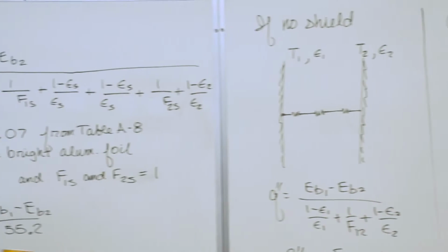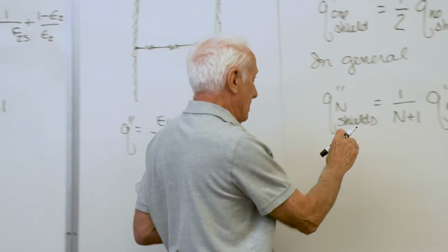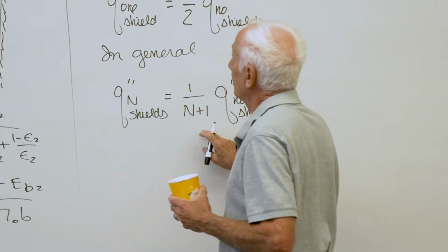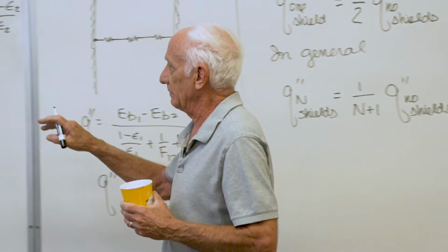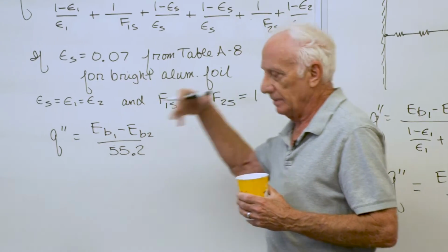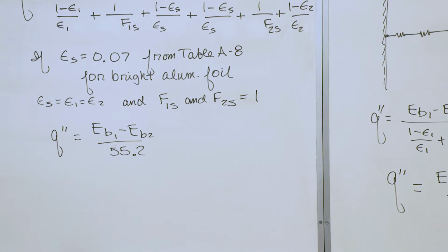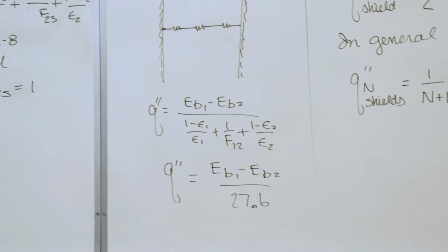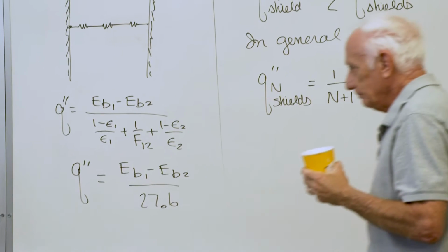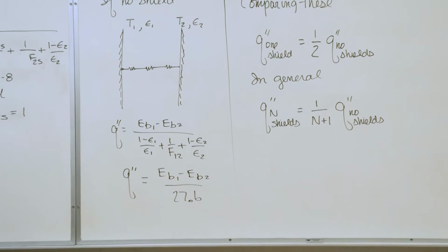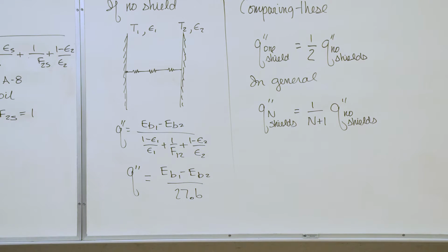So that's it. Now this equation right here is only valid if you let the emissivities be equal. If they're not, you're going to put the numbers in the right places. So there's a qualifier to that equation right there. For space applications, aerospace applications,